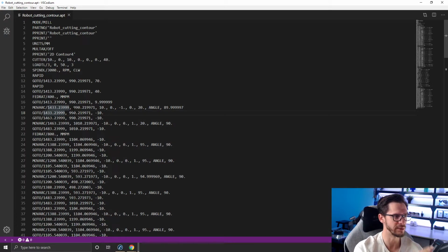It will take that information, bring it to RoboDK, and then from RoboDK translate that to something that is usable for your robot controller. So RoboDK here is kind of the middleman that does the translation first, but there is already some post-processor in some CAM software that can do the post-processing, let's say directly for KUKA, Fanuc, or other robot brands. But the thing that they don't do that we do is making sure that there are no singularities,